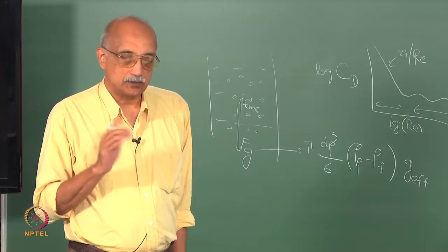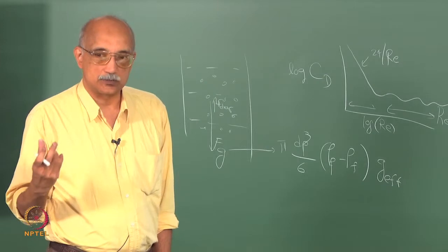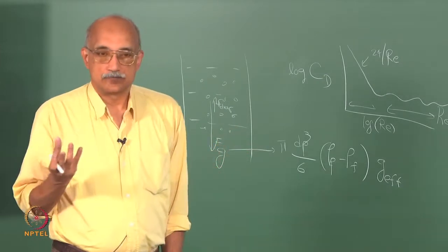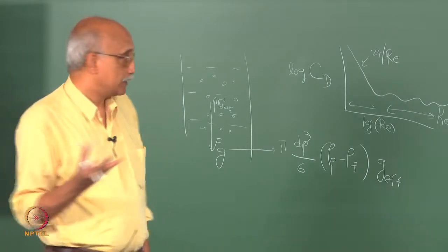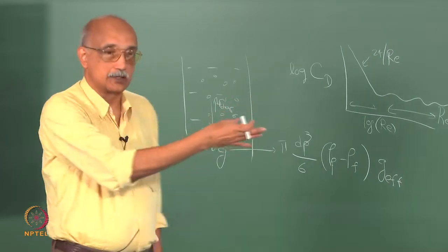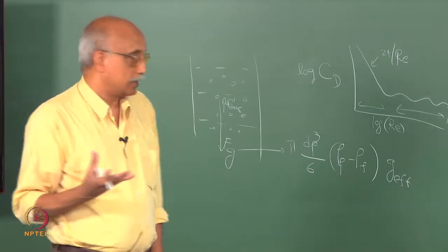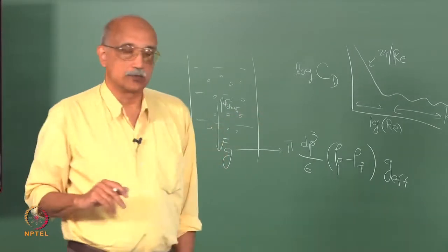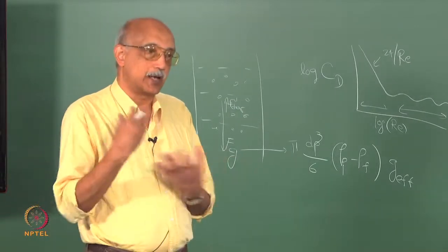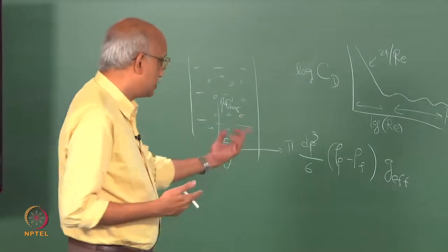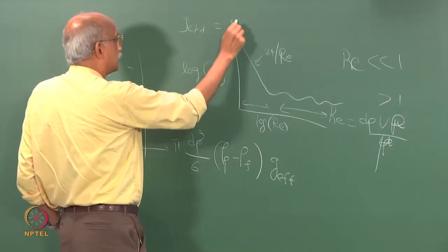Anyway, I think you can expect a couple of questions that look at derivation of certain basic principles. For example, you should be able to derive an expression for the terminal velocity from first principles in various cases, in the low Reynolds number case or in the high Reynolds number case. All you have to do is substitute the appropriate drag force expression, and also you should be able to derive the expression for terminal velocity in the case of a simple gravitational field or in the case of an applied centrifugal field. Now, this g value, g effective, can in general be written as the